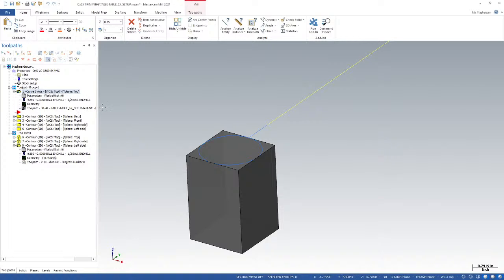For milling, it really doesn't come into play, other than if your post developer has created logic to read the axis combination, well then, all bets are off. You can actually have custom input that is going to change the output in the post. By default, it doesn't.